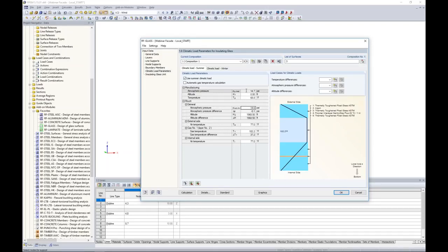Now we take a look at where the actual panel will be mounted. Let's assume it's going to be mounted somewhere much higher at 4,000 feet altitude, maybe where the atmospheric pressure is around 10.7 psi. The altitude is set at 4,000 here. Now the average temperature during the summer on the external side of the glass panel is fairly hot at 90 degrees. The gas then can get up to 102 degrees, let's say during the summer, and the internal side is set at approximately 70 degrees Fahrenheit.